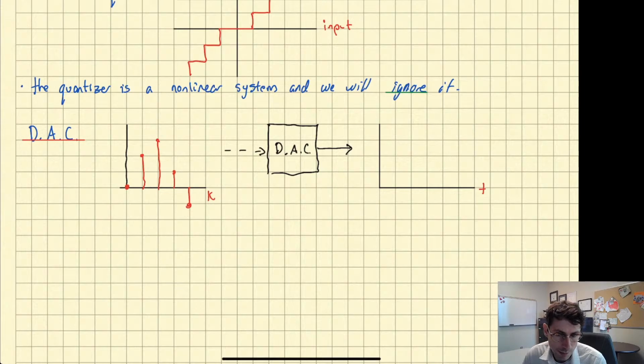Okay, so when you run this discrete time signal through the digital to analog converter, it's a circuit, right? It's still, at the low level, a circuit. So what it's going to do is look something like this. When the value jumps, there'll be a little transient that shows up. You'll see a little bit of rise time, and I'm exaggerating, of course, but there'll be a little waveform that shows up there. And similarly every time.